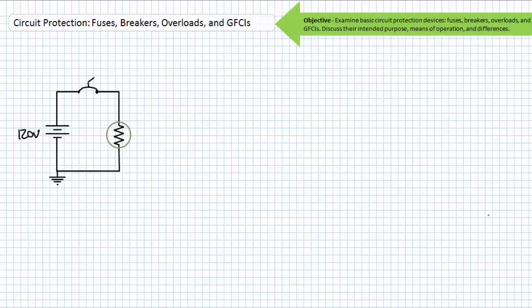In addition to its use as a handy reference point, ground actually serves as a means of protecting people from becoming an inadvertent path for electrical current. Intentional grounding is the purposeful introduction of a ground connection to ensure the safety of operators and the proper operation of protection devices like circuit breakers and fuses. Unintentional grounding is a fault condition and needs to be detected and resolved by protection devices.